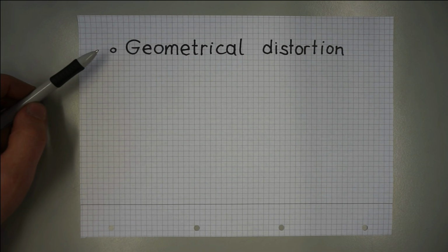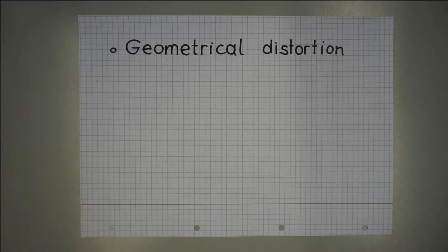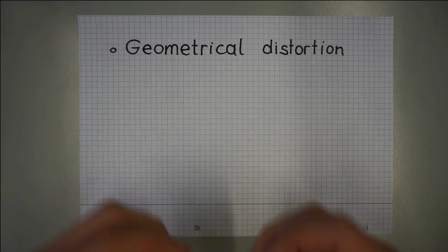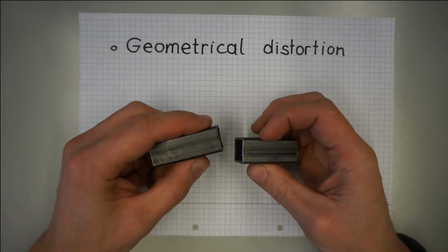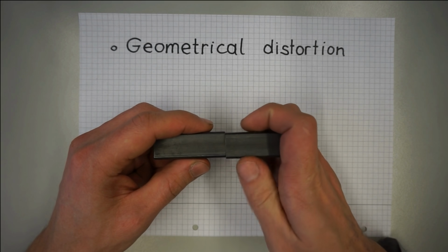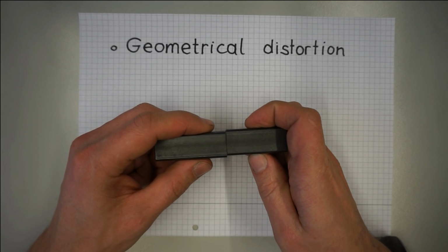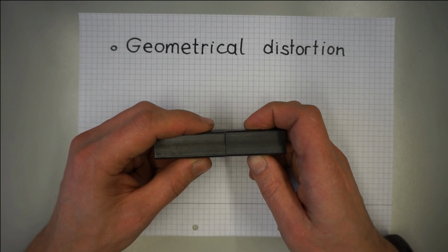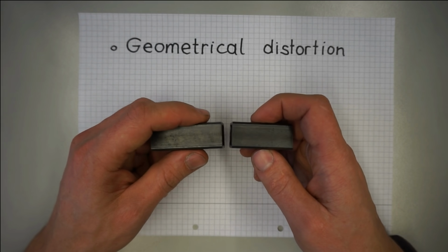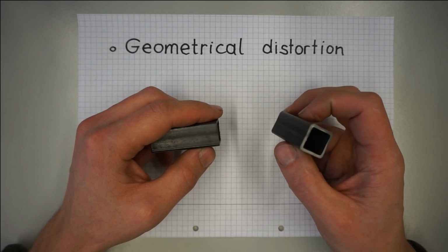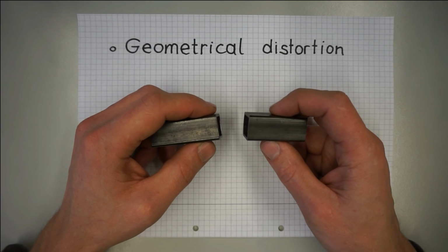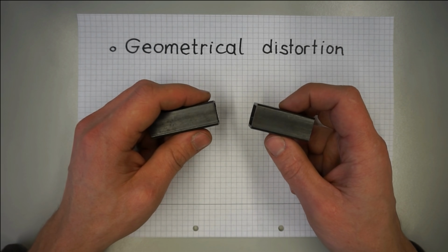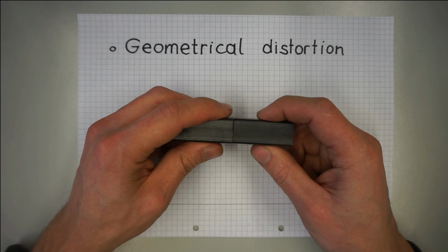We could narrow this term down to the problem of tacking with gaps and sufficient tacking. The neatest case that will give minimum geometrical distortion is of course a workpiece with zero gap fit up, like here, and little chance of the precuts to move on us as tacking progresses. This is a feature of good workpiece design and good prep work. In reality, however, we typically have to deal with more or less of a gap in the precut assembly, like here.